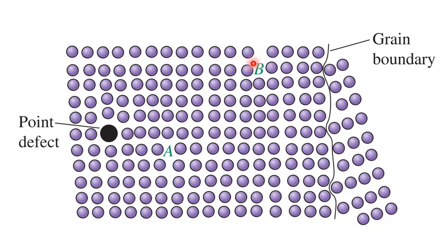Which means metals with a higher number of dislocations need higher stresses to deform. Or in other words, metals with a higher number of dislocations are stronger than metals with a lower number of dislocations, because of the interaction among dislocation motion.